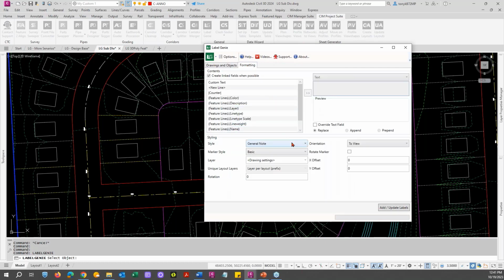And here's the tricky part. I made this style here that's called elevation. It's going to pull in this mark for it too, and that's going to put it at those spots that we're really looking for. Again, we don't have access to these things right here. So with that, I think I can just say OK. It's going to add 210 labels. It should put it at the corners and all of the other gray break points on those tabs.